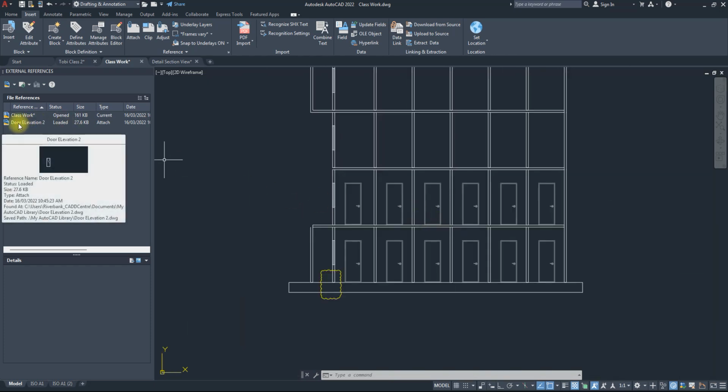Another thing is you can actually create an object as a separate file and just save it, not as a block. So I can open a drawing and just do WBlock and save it as a normal drawing. I can put it in my location, anywhere I want. Once I put it where I'm putting it, I can then load it also as an xref. But when you are creating that, you have to create it at the origin. Do you understand? If you don't want to make it a block, you have to create it at the origin.